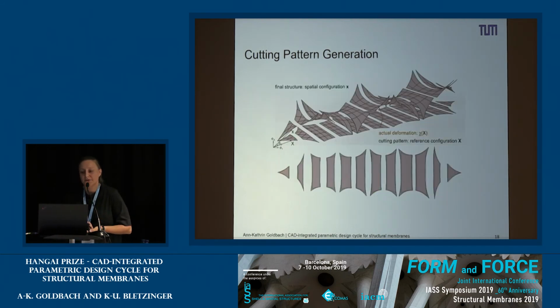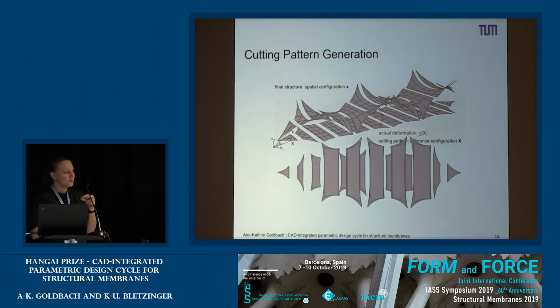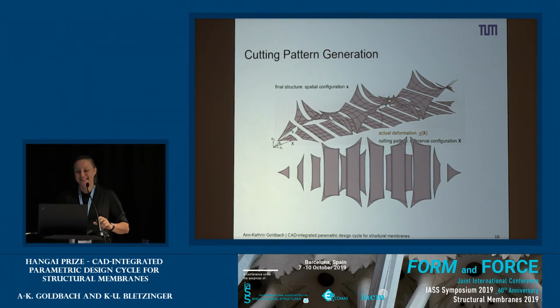So for the example I was showing you, the cutting pattern would then look like this, just dividing it into these stripes with the standard cut operations, and then applying this optimization technique of variation of reference strategy would give me something like this. So I hope you can see this. The blue lines, the smaller areas, are just the simple projection that I was talking about. And then after the optimization has been performed, the shapes, of course, look a bit different. Now, in this case, I just want to point out that compensation hasn't been taken into account yet. That's why they look so big.